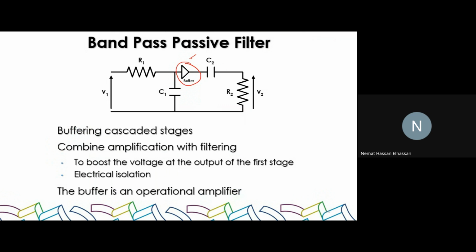Clear? Okay. Now, up till this point, you'll notice that all the filters that we looked at, all the implementations, were first order, right? And first order, we said, will have the roll off or the transition between high and low of 20 decibels per decade, right? And we said that 20 decibels per decade could look something like this, a gradual transition between pass band and stop band. But 40 decibels will be a little bit sharper.